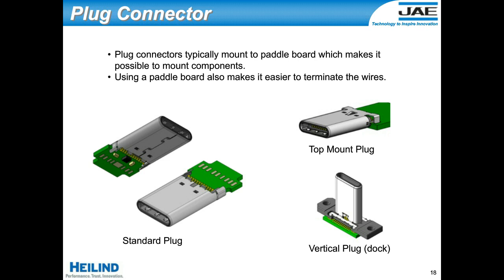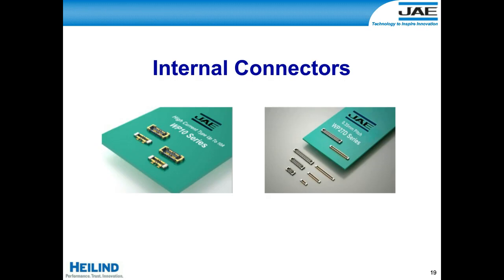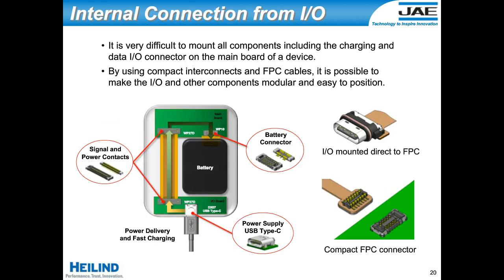So quickly, I want to go over some internal connection options. Obviously, Type-C, like I mentioned, has so many features and capabilities, but the internal connection is also just as important in many cases. This is just one potential block diagram of the inside of a portable, battery-powered device that uses a USB Type-C port. Typically, it's very difficult to have all of your components, including the I/O port, mounted to the single main board side of the device.